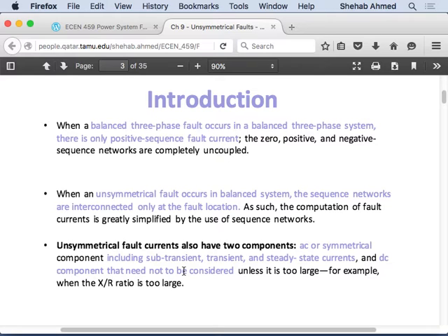The steady state value of fault current is the value of current that will remain in there until you clear your fault. You don't want your system to burn down, because this is going to stay there. The subtransient will die away. It will decrease, right? And then you will be left with the steady state value of fault current. The steady state value of fault current will cause temperatures to rise, arcs to occur, all of this stuff. Right? That's what's going to happen there.